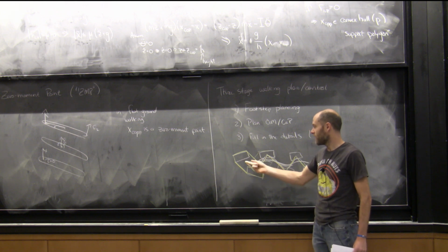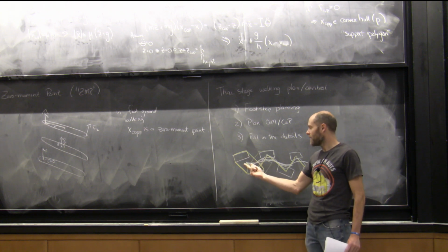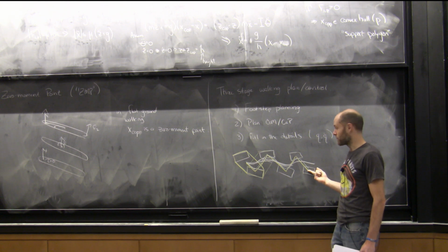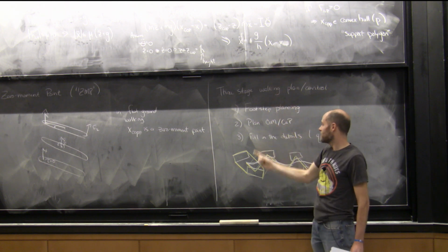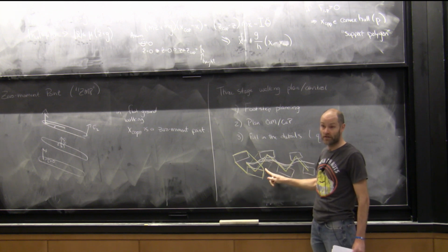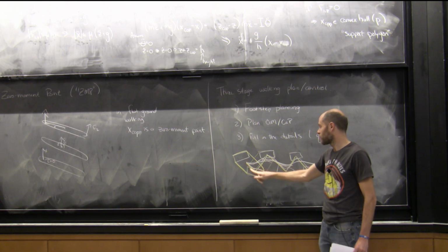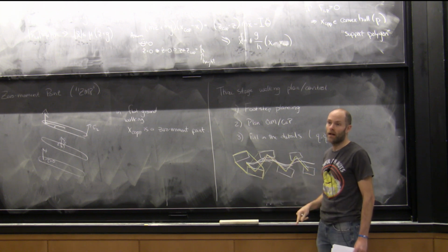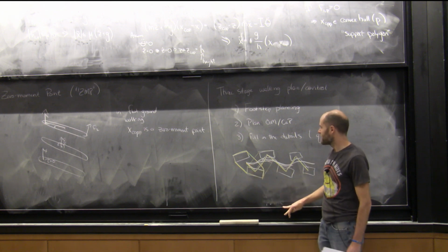But given a footstep plan, it used to be that people would just write the ZMP trajectory or the COP trajectory by hand and prescribe it. Now that we understand that it's a linear set of equations, and the ability for your center of pressure to stay inside a polygon is a linear set of constraints, you can actually use linear optimal control to jointly solve for your center of pressure trajectory and your center of mass trajectory. And I think that is in favor now. Certainly it's in favor in my world.